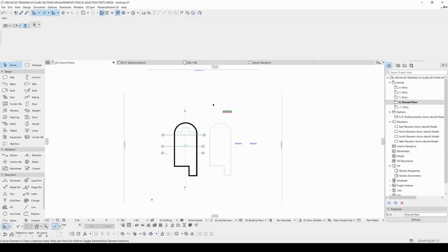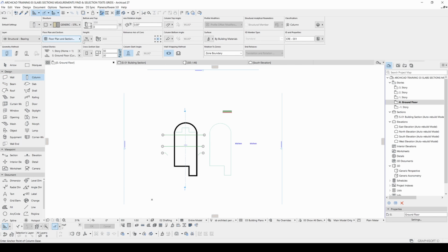First of all, in the left of the window you will see this design menu. And as you can see here, we can place walls, columns, and beams. When we click column tool, you will see more options. And actually, each option is the same with others. So you can change your starting elevation and elevation. You can change its direction or edit them after, or you can change its settings.